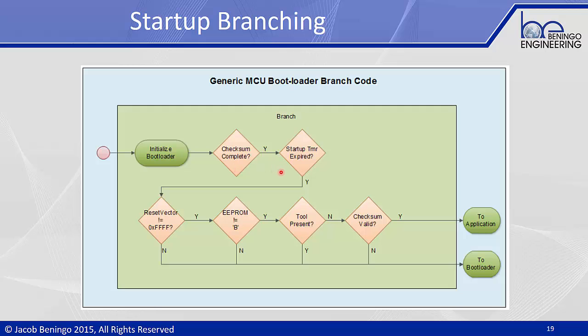So what I might do is set up a system timer in the background that's going to maybe wait 100 milliseconds in order to allow the checksum to be completed, but also, more importantly, to see if there is a programming tool present that wants to update the firmware. Once the timer expires, we can then perform a number of checks on the system. So for example, we might perform our reset vector check. Is the reset vector not equal to all F's?